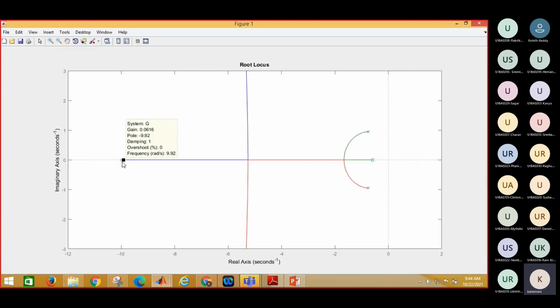So here in this location, my gain value is 1.11. My closed loop system has a critically damped response, there is no overshoot. My frequency is 8.919. Now I'll come to here. My gain here means the rate gyro sensitivity value. If the rate gyro sensitivity value is 2.07, I have a damping of 0.94, where the overshoot is 0.014 percentage.